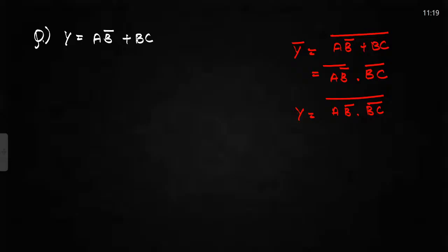Right. So here what we can do, we will always get complement. So for this one, 1, and for this B, we will get 1, and for this one, we will require 1 AND gate, and this one AND gate. So in total we require 4 2 input AND gates. So this is how you will do this type of questions. Now let us try to solve another question.